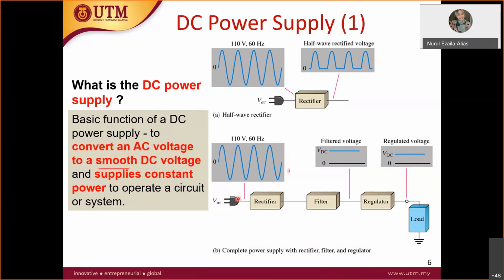So what happens in it is here. You have your transformer here, and this is your sinusoidal input. For example, the input is 10 volt. Then you have a rectifier circuit, which has its own function, and then you have a filter circuit. After you rectify the circuit, you might get output with noises. Then you filter out the noises, and you will be able to get a straight filtered voltage like this.